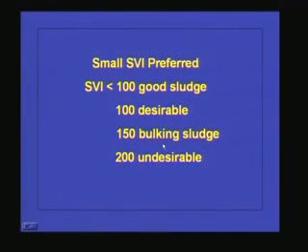As the microbial concentration in the aeration tank is reduced, definitely the performance of the system will decrease, because in the activated sludge process, or in any biological system, the workers are the microorganisms. If you reduce the number of workers, definitely the amount of work done by them will be reduced. That is the reason why a high SVI is not preferred in the activated sludge process.